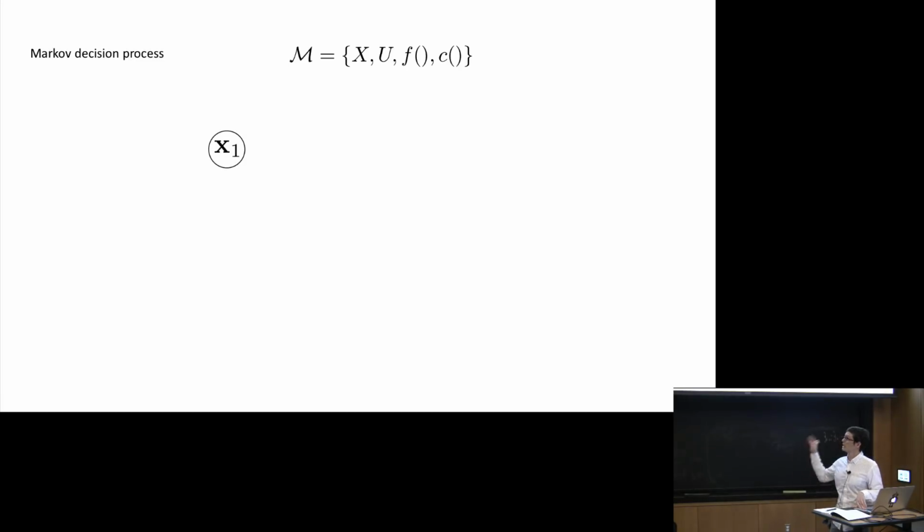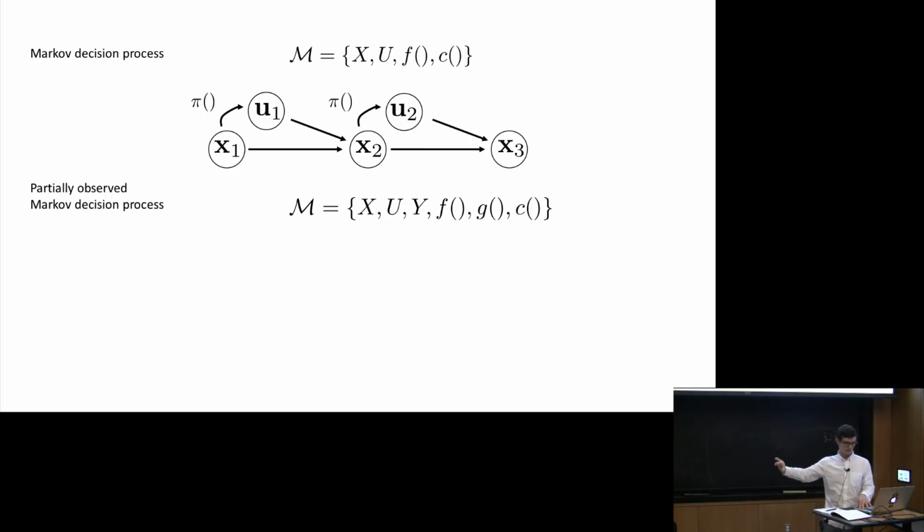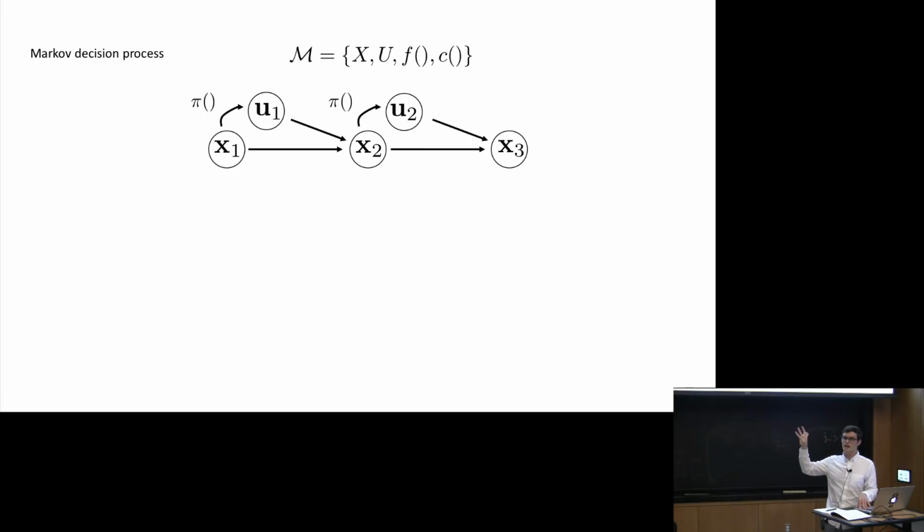And what that looks like is that we have some state. This is very important. We have some state, and then we have some policy which decides what to do based on our state, and then the two things, being the state and the control input, bring us to our next state. And once our next state is defined and we know that state, we can forget everything from before, because now we know our state, we can then decide our control policy, and again our dynamics send us to our next state, right? So this is the regime that most of the class has been operating in.